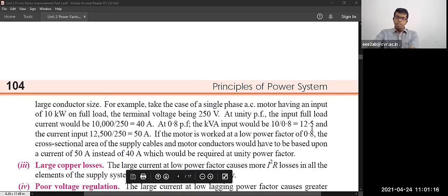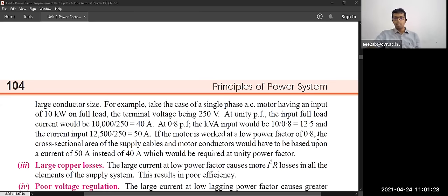Also, if they are not maintaining in the power substation, what they will do is simply switch off the power in that particular feeder where that industry is connected. If they are maintaining a lower power factor, like 0.7 or 0.6, the substation will know by default. In the substation, the power factor will be increasing, so they will simply cut the feeder for 2 hours, 3 hours, so that a particular machine will not work for 3 hours.